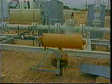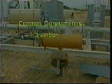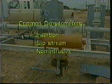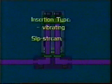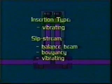There are basically 3 types of densitometers: the insertion or inline types, slipstream or strip sampler type, and the non-intrusive type. Densitometers can also be characterized by measurement method. All insertion densitometers are the vibrating type, while slipstream densitometers can be either balance beam, buoyancy, or the vibrating type.